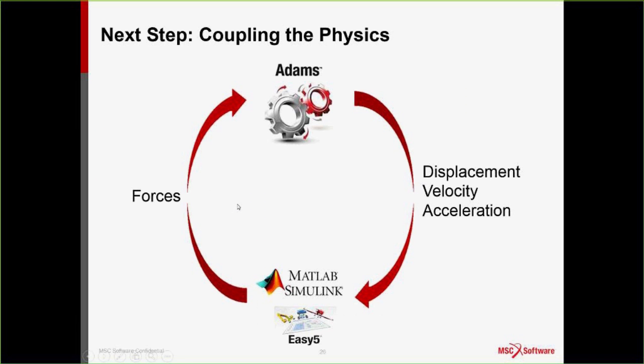So in today's example, we are going to introduce a mechanism called cosimulation, which means the Adams solver will calculate the Adams model, and the MATLAB Simulink solver will do the calculation for the Simulink. So in this scheme, each solver is doing its own specialty. We're not trying to use one solver to calculate both models. We're asking each solver to be responsible for their own model. So in this way, you will get a pretty precise prediction for your entire system coupling.